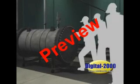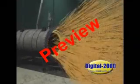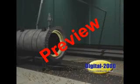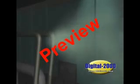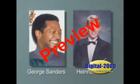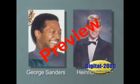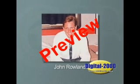Just after 2 a.m., 12 hours after the startup attempt, 3 night shift workers approached the waste tank to clean it out. The workers began to unbolt the cover of the tank. After they had removed half the bolts, the extreme pressure blew the 1,750-pound cover off the tank with explosive force and ejected hot plastic over a wide area. The waste tank recoiled backward, breaking hot oil pipes and creating a vapor cloud which ignited 6 minutes later. 2 of the maintenance workers were killed instantly when the tank cover blew off. The 3rd was pronounced dead on arrival at a hospital.